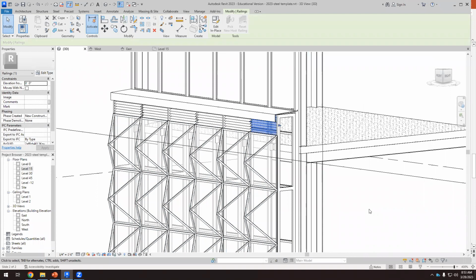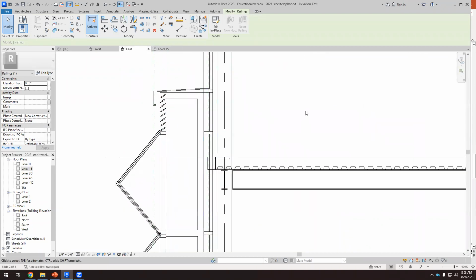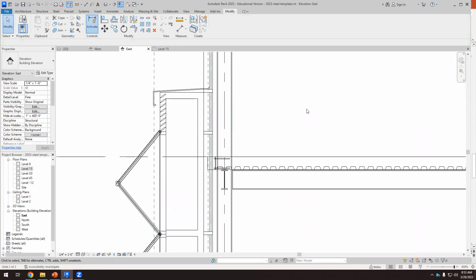something that first, if it's like this, okay, so let's understand that. If we have these louvers in this position, first they are protecting this cavity from the water. In the event that the water can go there, they are sloping out, so they get rid of water. And now if it's open, it's ventilated. If we want to close that louver, we have a shape that is like this.